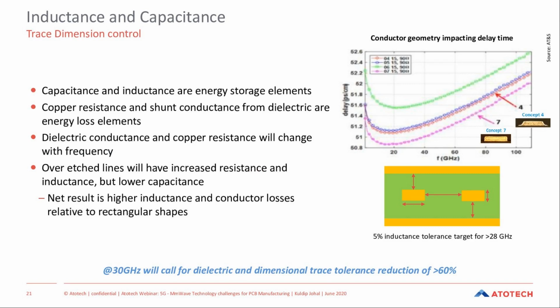Another factor on impedance control, which is a very important factor, is what I would say is the trace dimensional control consistency, which is the line width and height and space, are critical for signal integrity. And you could say, well, this is mainly driven by key parameters such as lithography. And you could say it depends on my differential etching approach.